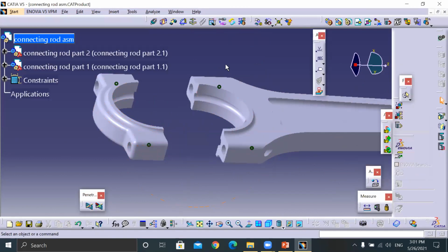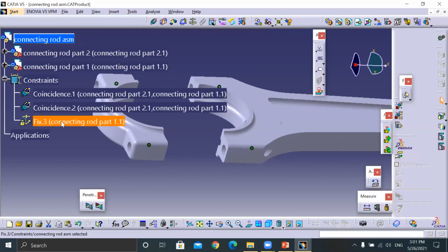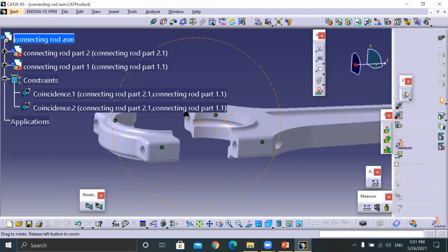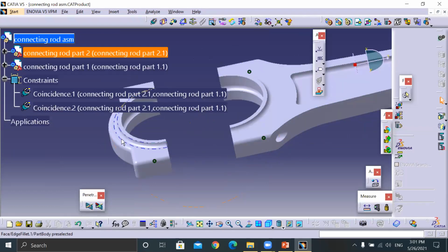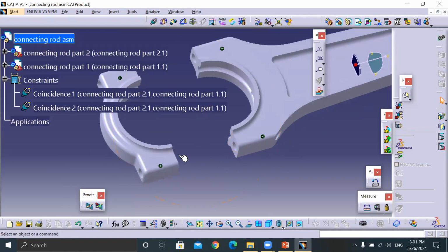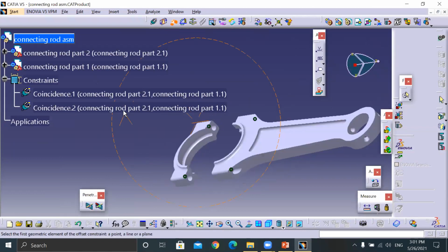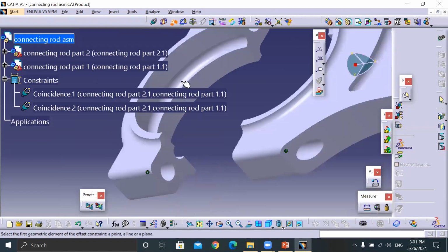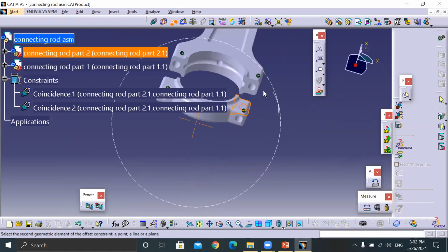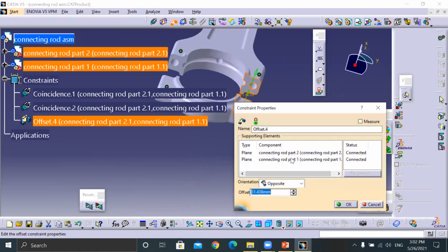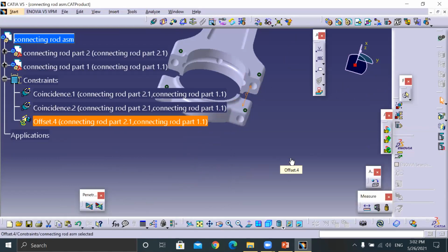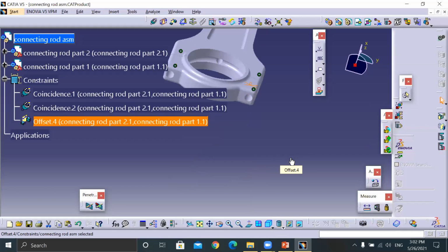Okay, delete this text. Just for movement, okay, because it's already in contact now, that's why it is not moving like this. Okay, but actually there is some gap. So here what do you have to apply? Offset. Yeah, offset. Contact constraint. Okay, first select your moving part, then 0, enter. Update. Now it's done.